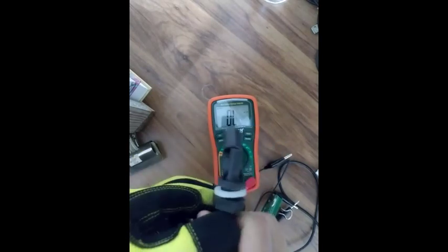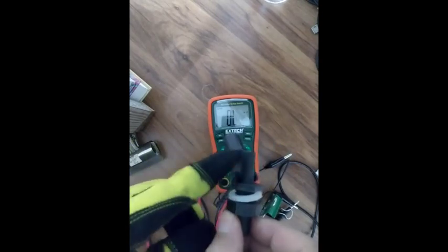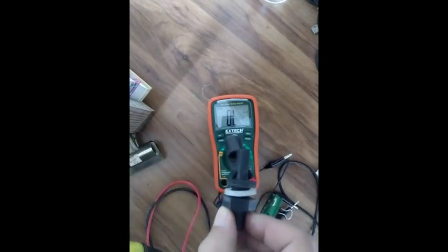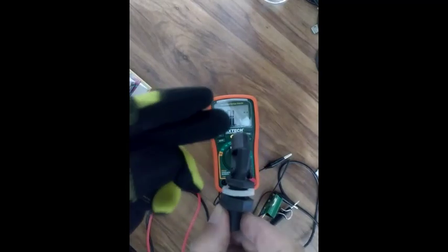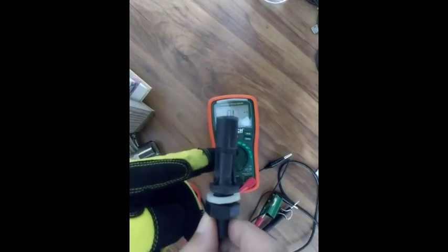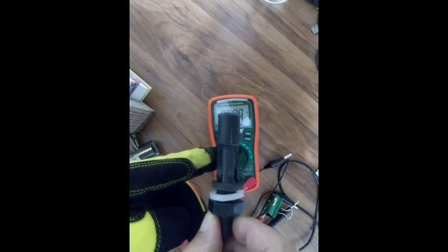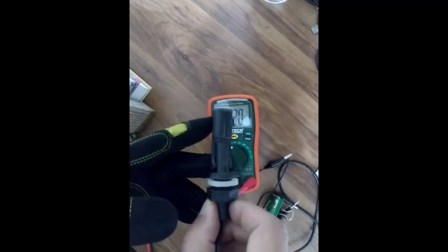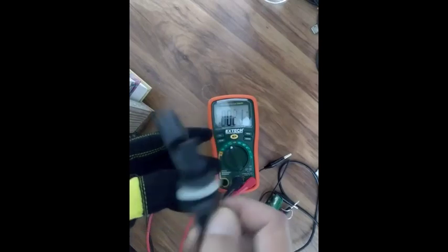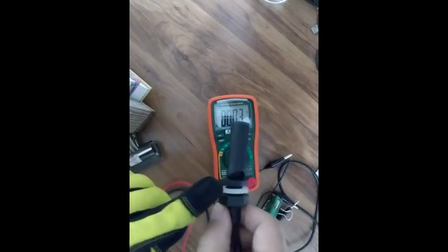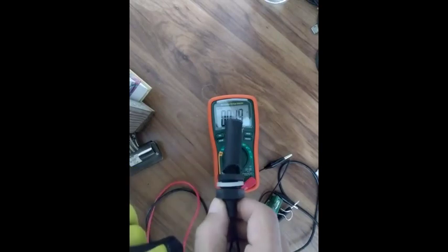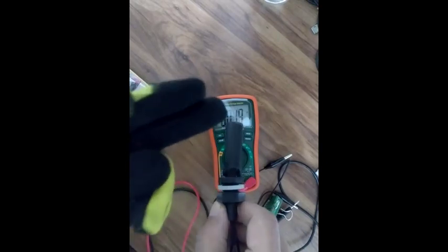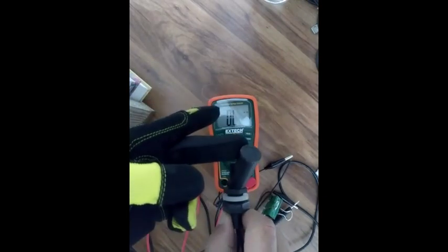If I install the float like this, it's what we normally call normally open. So when the liquid level rises, it will close the contact, indicating that the liquid is right at this level, whatever distance you install this within the vessel. Now, the second way that you can install this is like this. This is what we call normally closed. So when the water rises, it will pop open, and then you have an open loop condition.